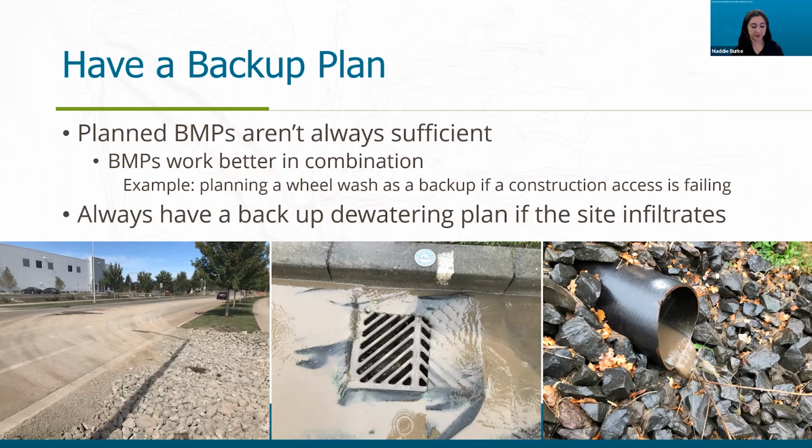Jordan also mentioned this with the sediment tank, but you always need to have a backup plan for dewatering if your current dewatering plan is that your site infiltrates. Maybe when you had the tests years ago in a dry season, the site did infiltrate, but if you end up with water on your site, if your contractor ends up with water on their site, they need to have a backup plan for how to get rid of the turbid water and properly release that without negatively impacting the stormwater system.